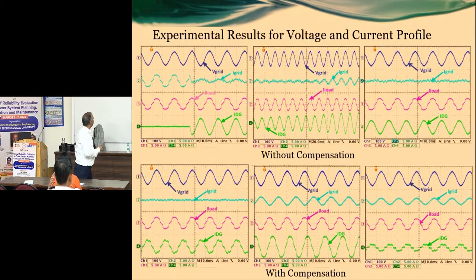Here I am generating less. So some part I am drawing from here and some part I am taking here, so to meet my load demand. Third one is the load curve. So you can see that experimentally we have proven that if we can control this generating current or grid side inverter current, then the harmonic inside the grid can be minimized. But in this case, you are introducing the harmonics. So this is the beauty of the system.